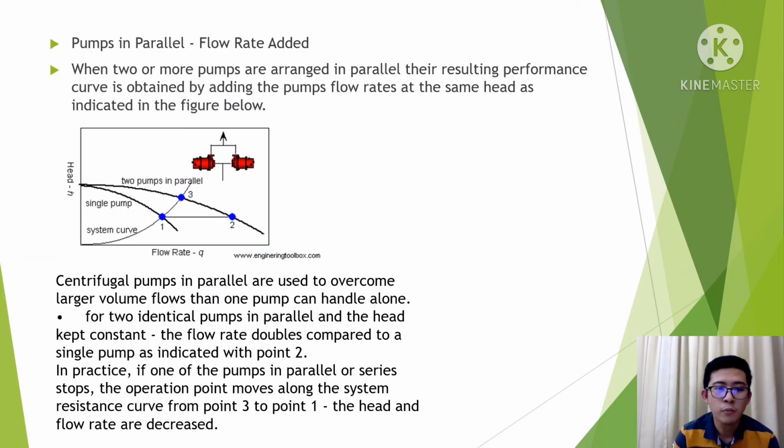When we come to pumps in parallel, it is when two or more pumps are arranged in parallel and their resulting performance curve is obtained by adding the pumps' flow rate at the same head, as indicated in the figure below. Centrifugal pumps in parallel are used to overcome larger volume flows than one pump can handle alone. For two identical pumps in parallel and the head kept constant, the flow rate doubles compared to a single pump